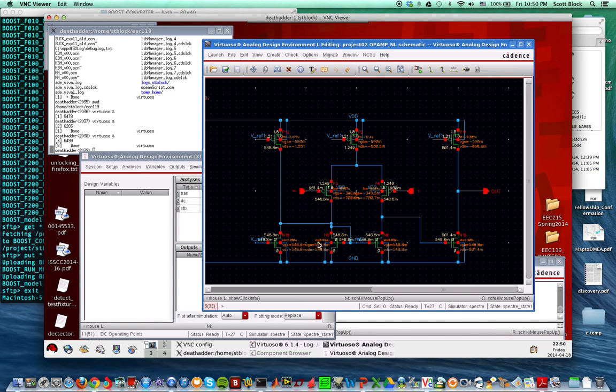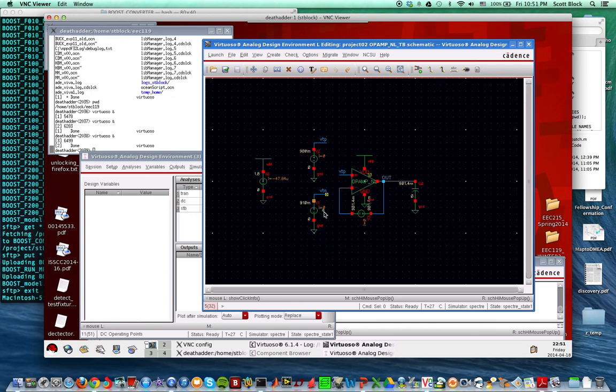What I'm doing here is I'm trying to match these voltages better, so I'm actually bleeding off a little bit of current into here, so the currents will match between these guys a little bit. So I'm using this reference point to set, basically I generated another, this is a current mirror here, this voltage is fed back into here, and then I'm feeding from my original current reference a current here, so some current goes into there. So let me show you the stability analysis.